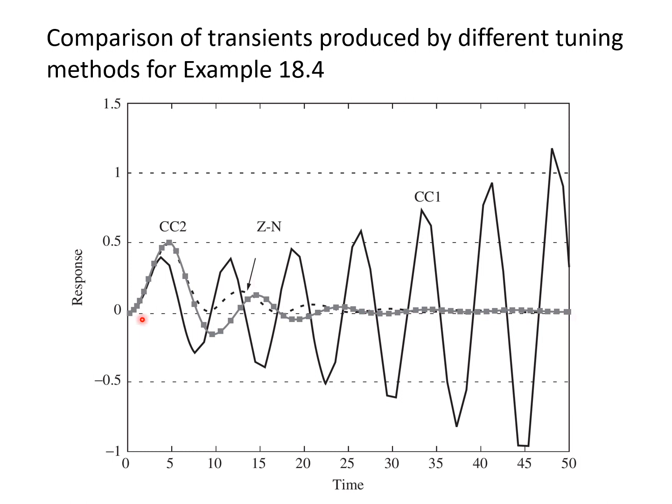The Ziegler-Nichols method has roughly the same overshoot, but looks slightly faster going back than Cohen-Coon 2. But Cohen-Coon 2 and Ziegler-Nichols are very close in terms of response behavior, but not Cohen-Coon 1, which is way off.